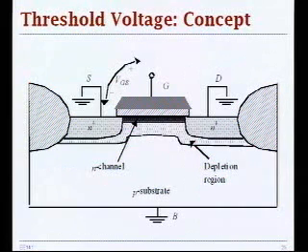So let's take a look at NMOS device here. We can identify N plus source and drain regions, P substrate, and also gate electrode, polysilicon gate with thin oxide between the two. The thickness of this oxide is in tens of nanometers range in this technology that we're going to be using in the class.